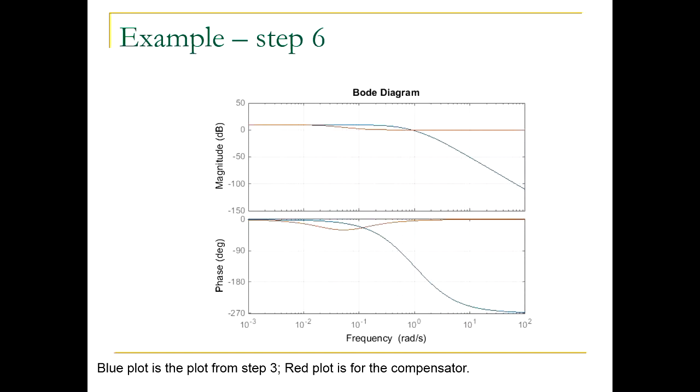So anyway, going back to what we set out to achieve. We are looking for a frequency at which red and blue magnitude plots are opposite sign but the same magnitude. So it would be roughly somewhere here, right? And then at that frequency we need to add the phase plots to get the amount of phase margin, right? So that's how you would do it without really having to draw the added plots. You can directly use it as it is here to basically answer the question, what's the phase margin for the compensated system. Are there any questions regarding this?